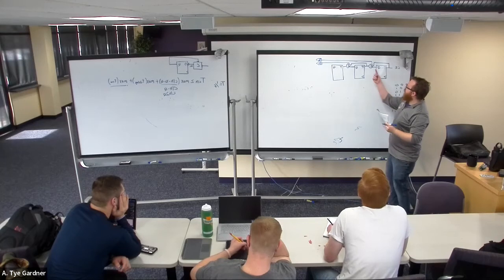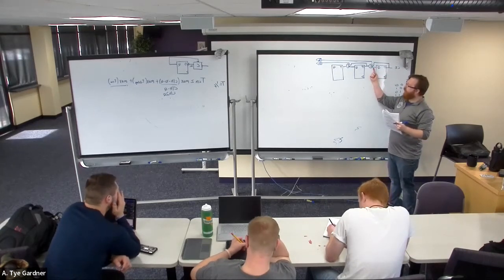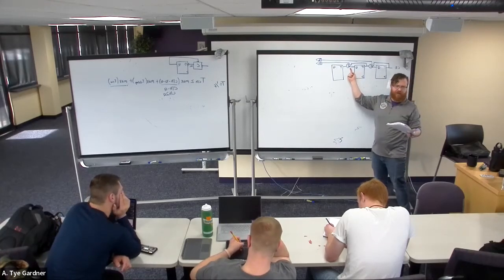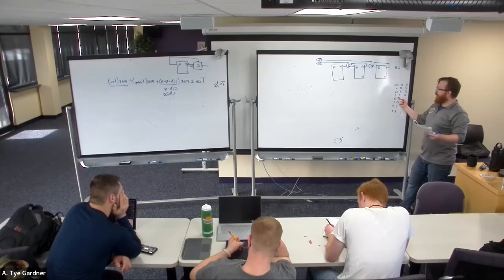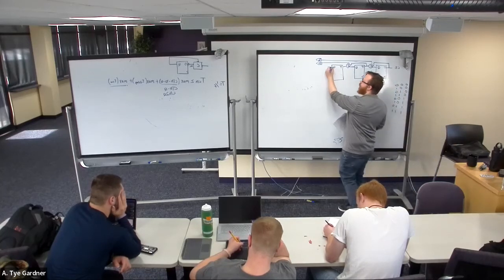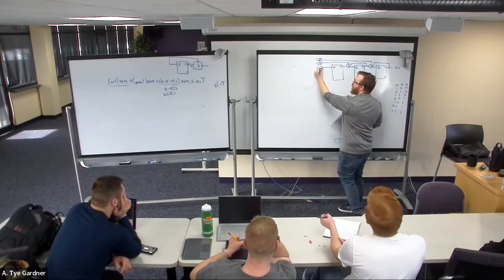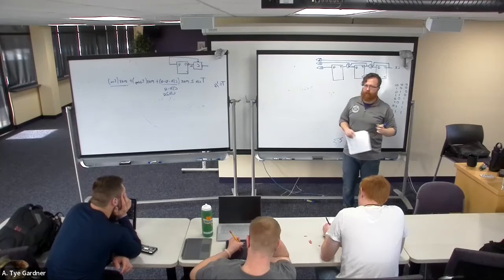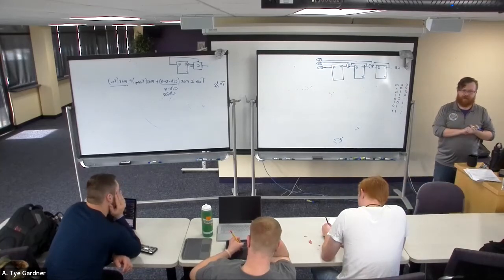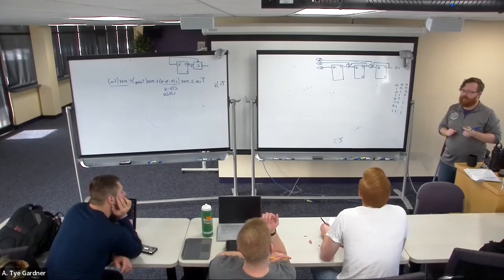Well, now, if my clock is enabled and I'm 1 and I'm 1, so my clock is turned on and I have 1, 1, this one will toggle. And on and on and on. If I need an 8-bit counter, I can just copy and paste and keep going.